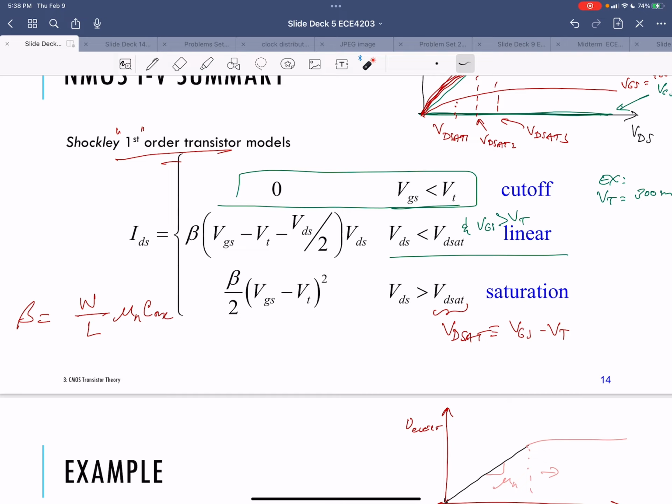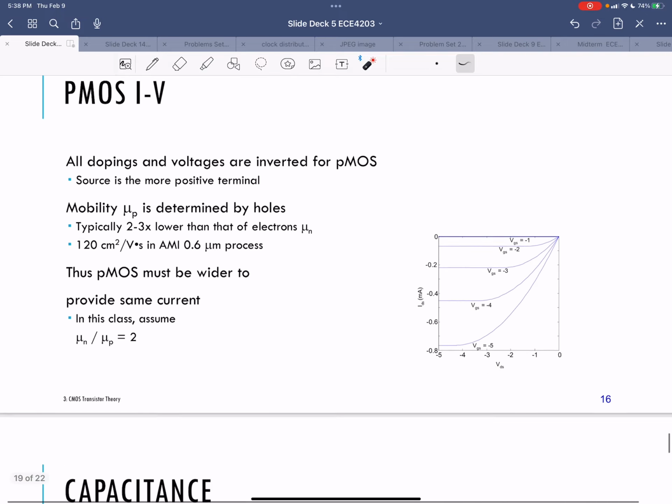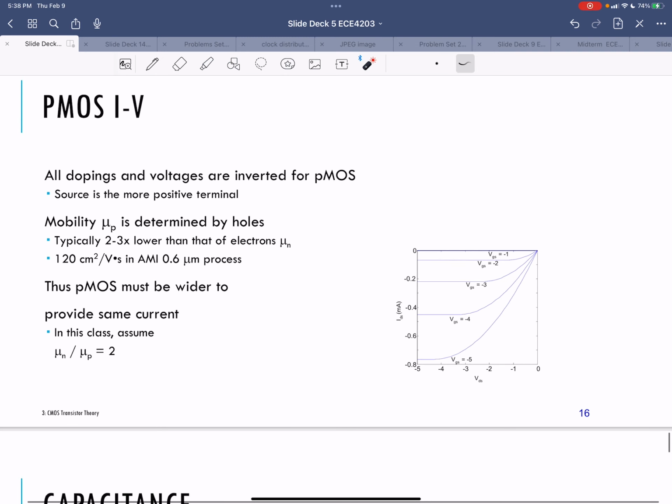As you'll see in your simulation, for all the currents versus your VDS, you need to go to a negative VDS voltage, meaning that your drain has to be below your source voltage for this current to flow, and your gate has to be below your source for the current to flow.